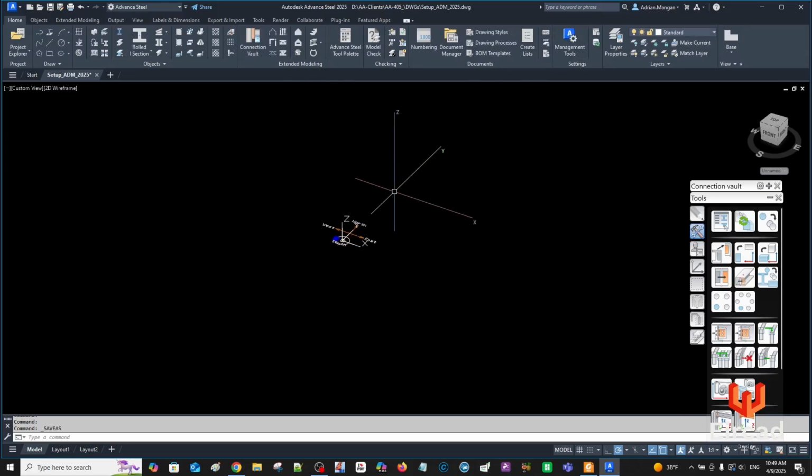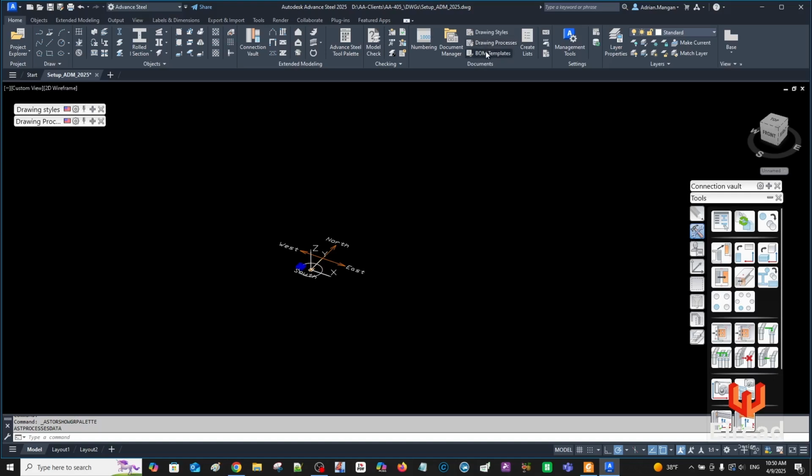So we've changed some of our backgrounds, something that's your drawing styles, your drawing process, your templates. We haven't created any of our own yet, but we don't need the system ones because they're already copied in the user ones. So all these ones, to get rid of this flag, so every time you don't have to turn this on and off. It's not that much of an annoyance, but it's just better to get rid of it. So you can see right now you have the option to switch from the system to the user, and the same in all of these.